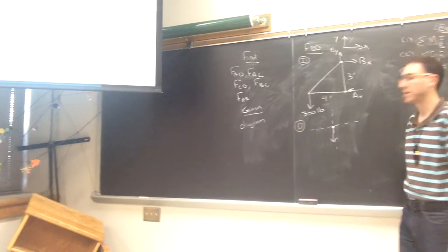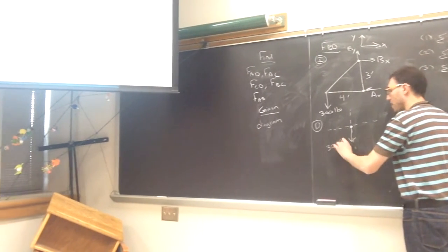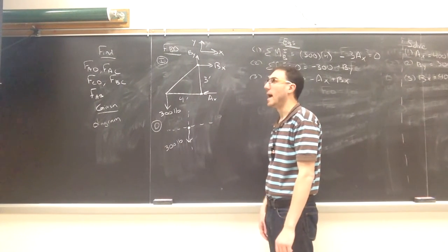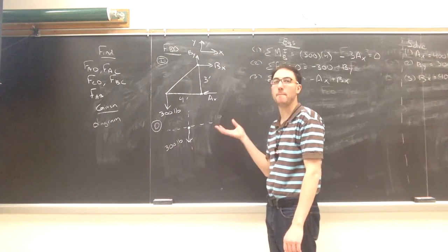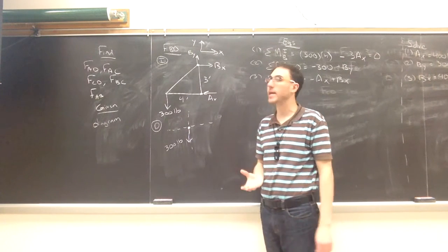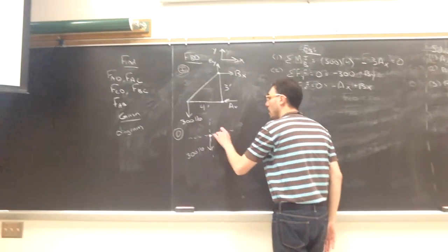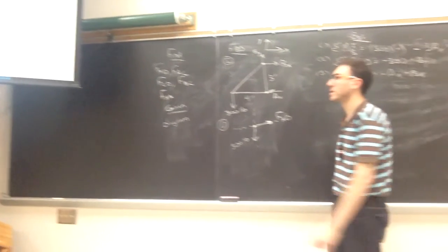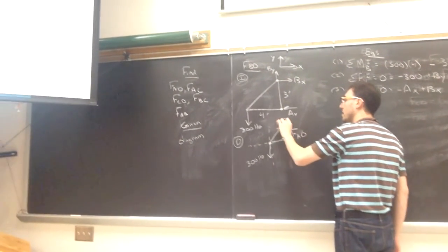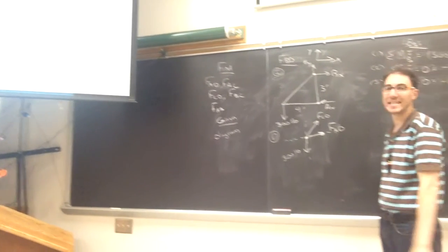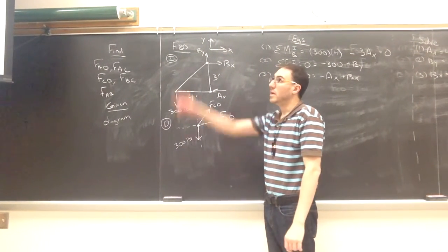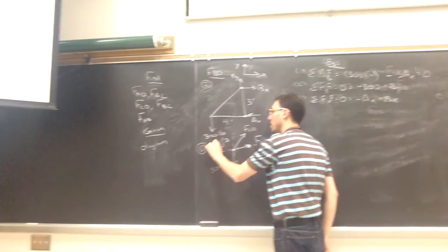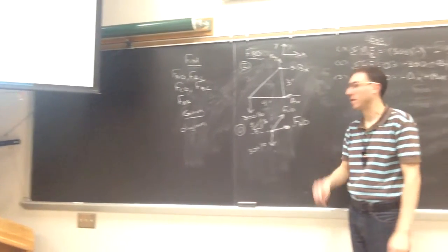So I copy all the external forces that are on D, that 300 pounds. There's no supports here. And I have to include what the members are doing to D. I'm going to, again, always assume tension here. I'll assume that AD is pulling to the right along its length, and that CD is also pulling on point D. This would go as a 3, 4, 5 triangle. So I can express this direction using a ratio triangle.